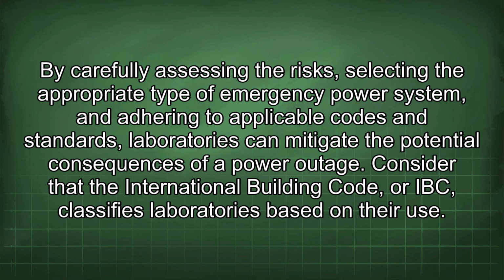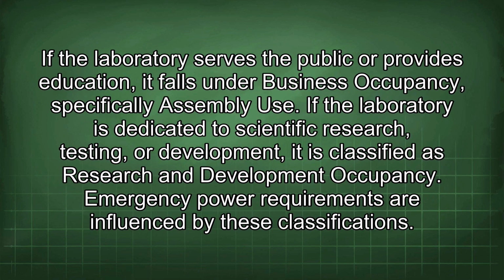Consider that the International Building Code, or IBC, classifies laboratories based on their use. If the laboratory serves the public or provides education, it falls under business occupancy, specifically assembly use. If the laboratory is dedicated to scientific research, testing, or development, it is classified as research and development occupancy. Emergency power requirements are influenced by these classifications.